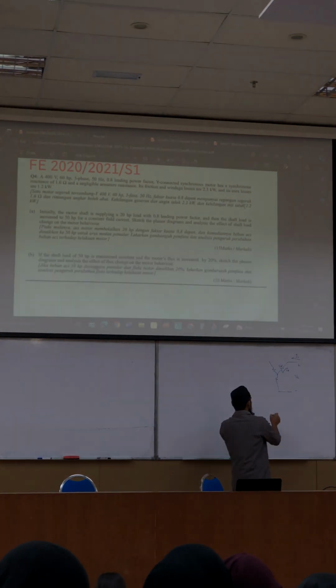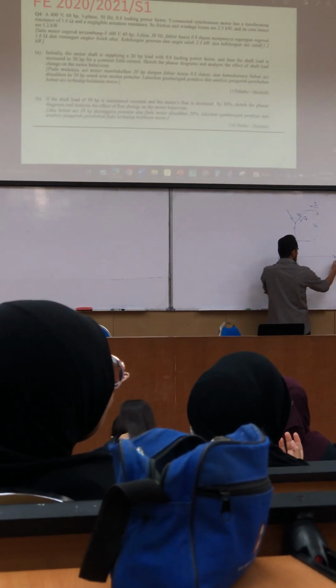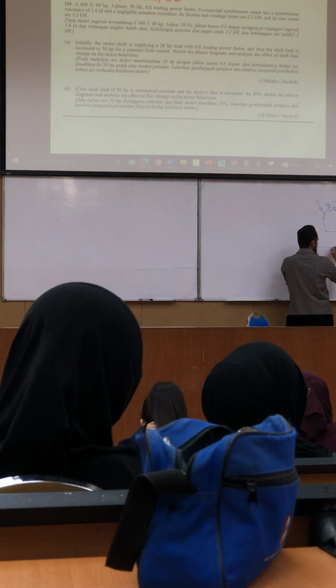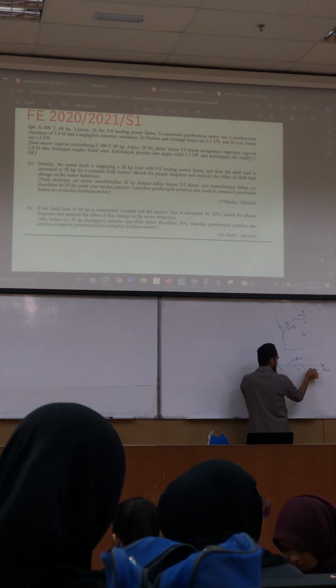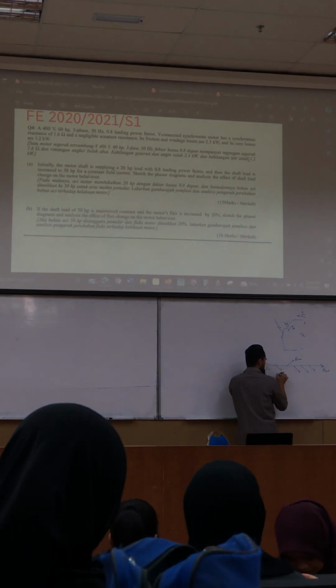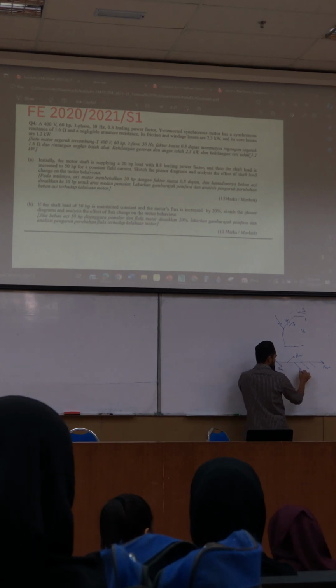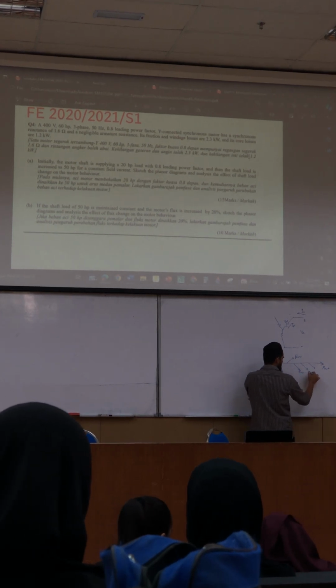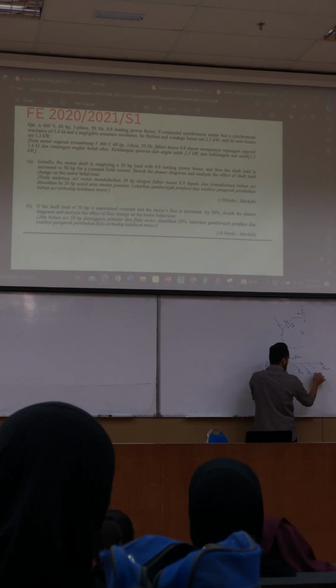To talk about loss, you have to use a fishbone diagram. P in, P out, P converted, and in between that you have loss. So these are your losses: P electrical, P core, P friction and windage, it doesn't matter which one comes first, and P stray.